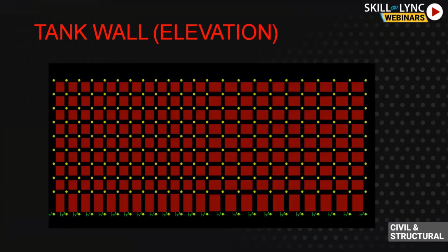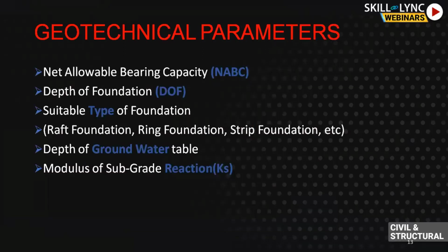On the bottom, all the soil spring values. How to assign the soil spring values, I'll tell you in the geotechnical slide here. Before proceeding to any project, you need to speak with the geotechnical engineer, process engineer, HVAC engineer, and environmental specialist. What do you need? Usually geotechnical engineers give you the bearing capacity, but you also need the depth of foundation and the suitable type of foundation for this type of soil.